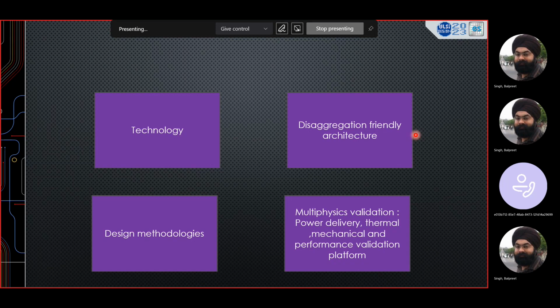It's not easy because remember, when you are trying to drill through silicon, such a long copper pillar, there are reliability issues. You have to make a certain diameter of that piece. Not just that, when you try to make such a long copper pillar, in the process there are challenges. Because when you try to create active, even digital circuitry next to the neighbor, there could be a potential asymmetry, a potential problem. How do you create a separate clearance zone over there? Those are the technology areas where we need to focus.